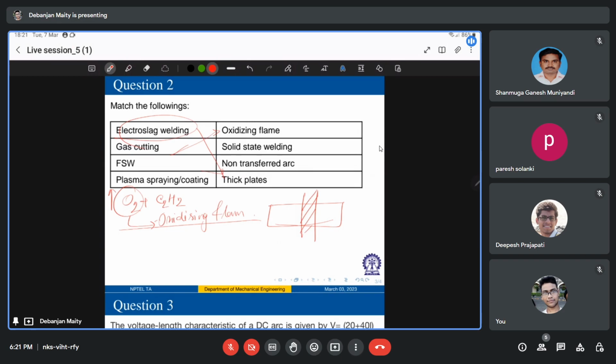And then I am not sure whether you are familiar with friction stir welding or not. Friction stir welding is a solid state welding technique where you have a workpiece like this, and you rotate your tool, which has a pin, of course. This is your pin, and this is called your shoulder, and this is rotating and plunging against the workpiece.